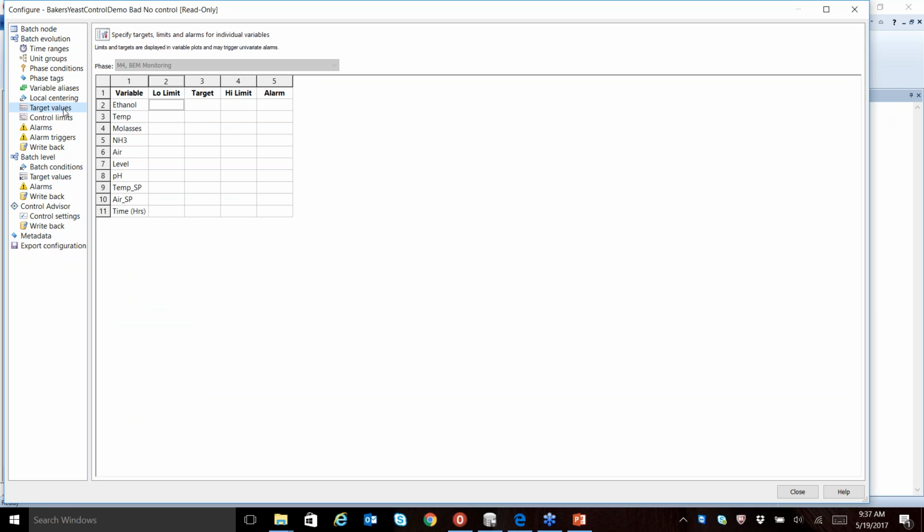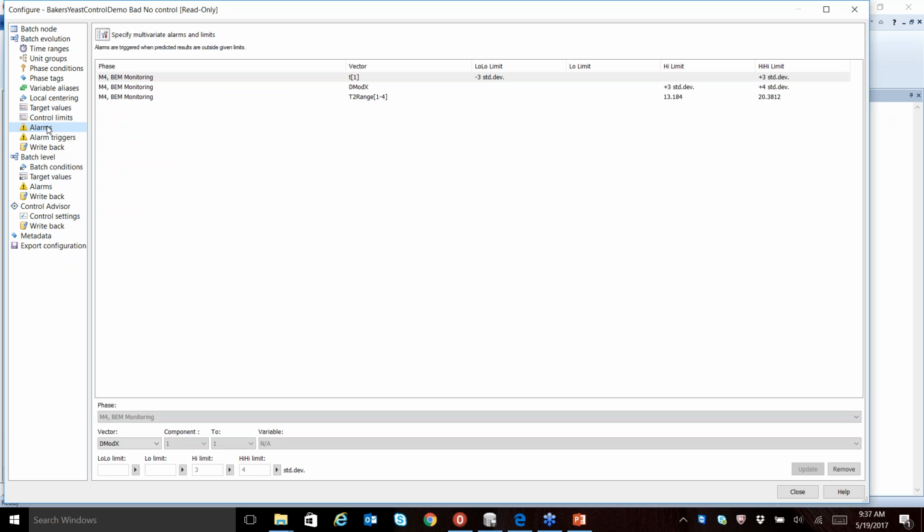You can then also, like I mentioned, configure all these different alarms, which these basic green, yellow, red operating principles are running on. You can have both multivariate alarms as well as univariate alarms. You can configure your alarms and target limits on individual parameters and add that together with multivariate alarms, for which we of course recommend using T2 Range and DModX in combination, particularly together with an important score, and define alarms for those.